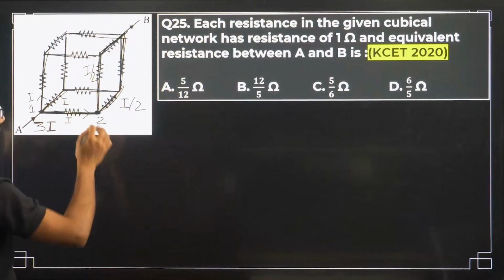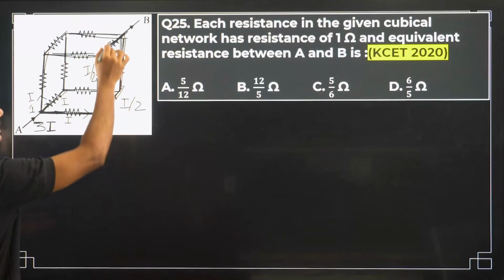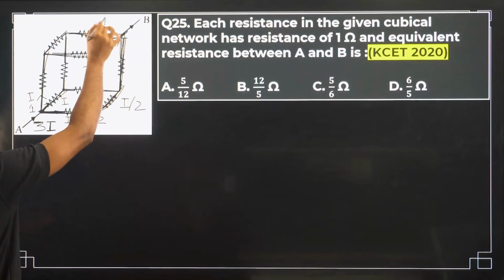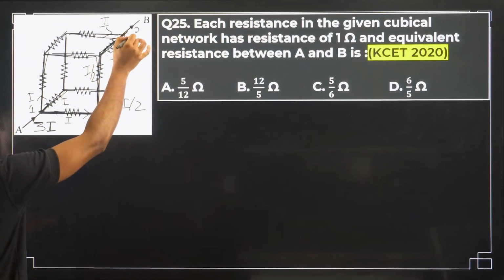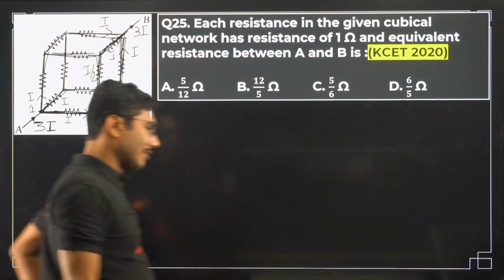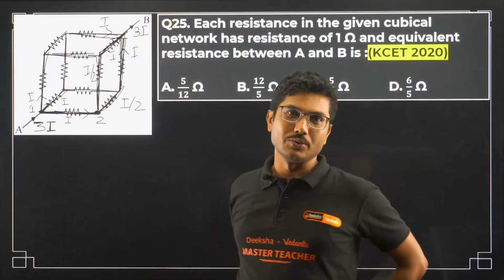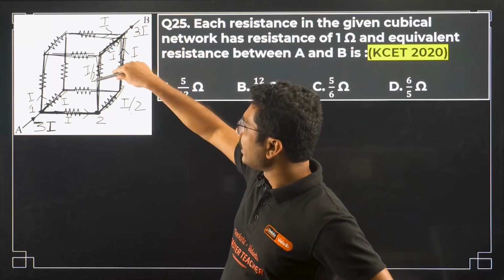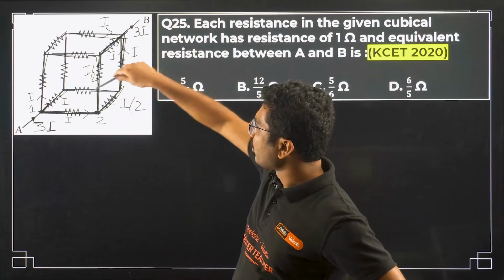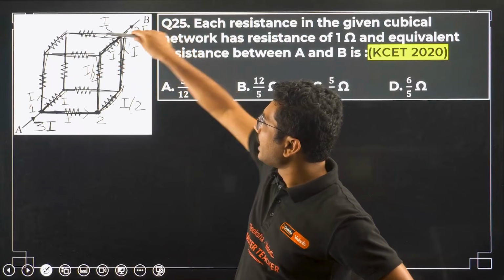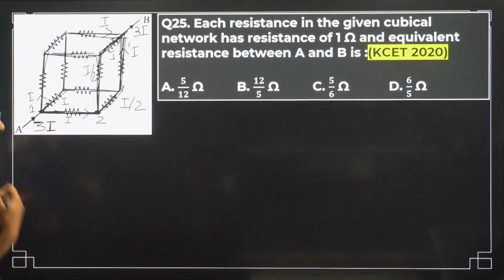Now we don't need to do anything else. This is sufficient. Once all the currents reach over here from all directions, the current going in should also be I, so that the exit current should also be 3I. That is the conservation of charge. Whatever current goes in, the same current should go out. So I by 2 from here and I by 2 from here, they add up to I. That's how you get I. So this is how you solve this. This is a very specific circuit.